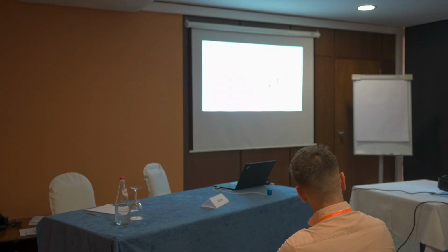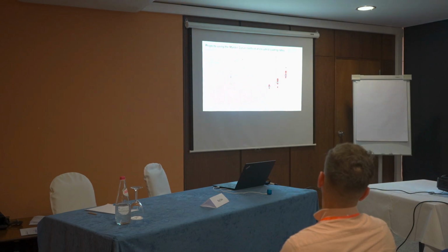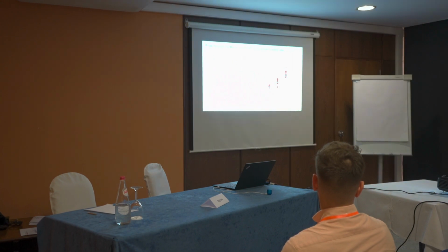There are some known reasons for that. One is that at very high loading rates you have a temperature increase at the crack tip from the dissipation of the energy from the plastification. This means that the effective temperature near the crack tip is a little bit higher, and this shifts the result. But the other thing is we found local crack arrest on the fracture surfaces, and this is the second reason for this deviation from quasi-static behavior.